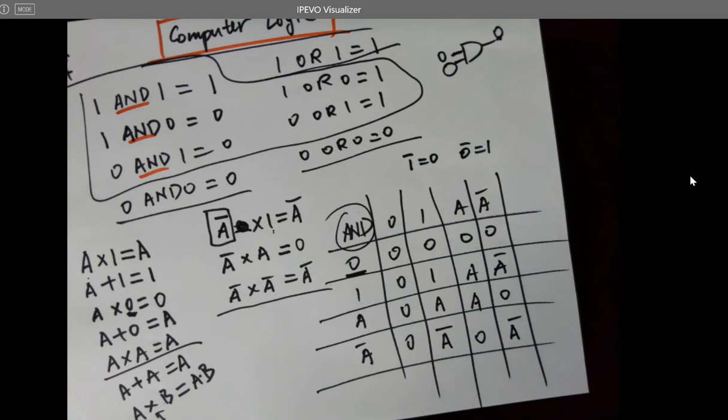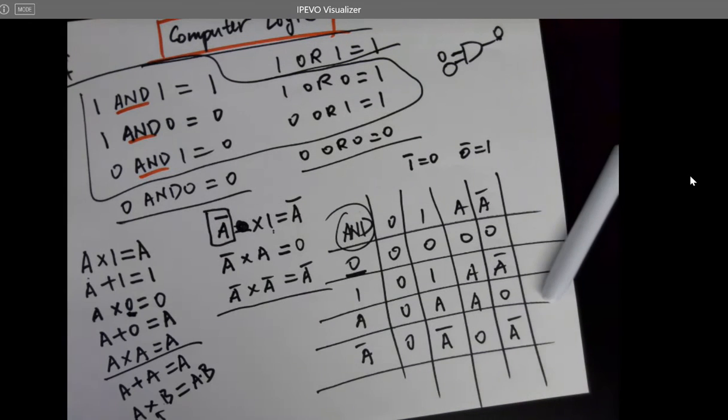Any questions? That's critical, okay? When you're programming a microcontroller, you need to understand what's going on. So first, understand the voltages. Why? Because if your circuit's not working, you know how to debug it. You grab these 2 cables. If you understand voltages and currents, you know where to probe it.